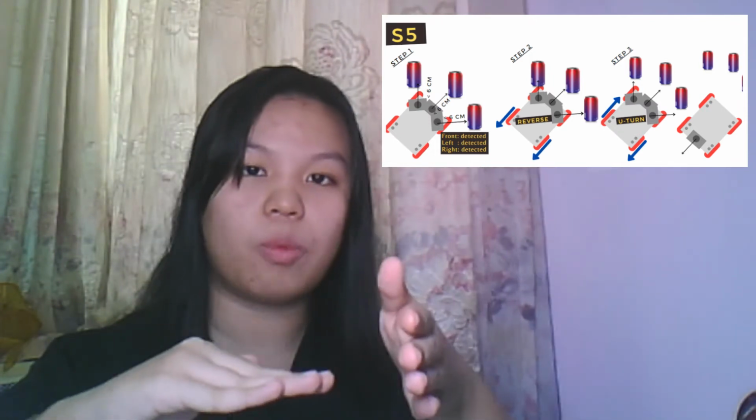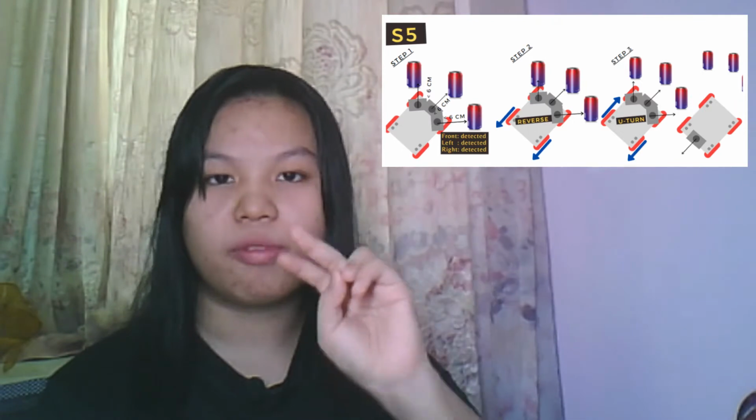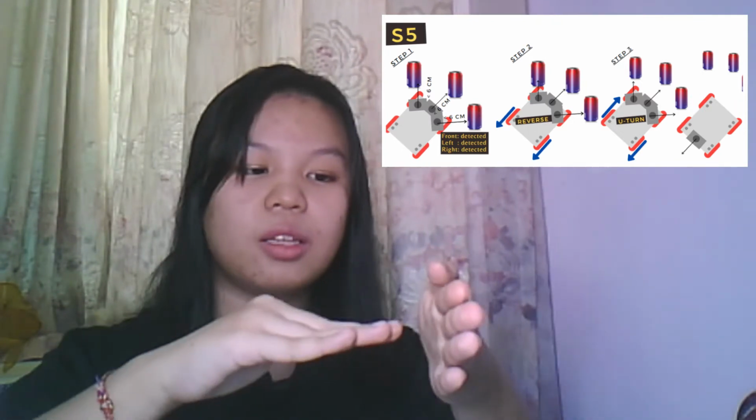So what we do is that we're going to reverse and then make a U-turn. Okay, so when we combine 2 and 5 together, what we see is that the front detector detects, check, we're going to stop a few seconds, and then we're going to need to check left and check right. The fifth scenario is after checking left and right, both have obstacles, so we're going to reverse and make a U-turn. So that's roughly the 5 scenarios that we will be doing today.